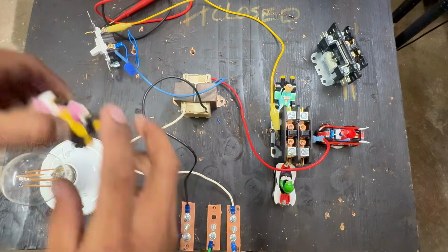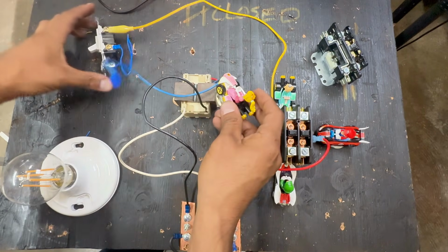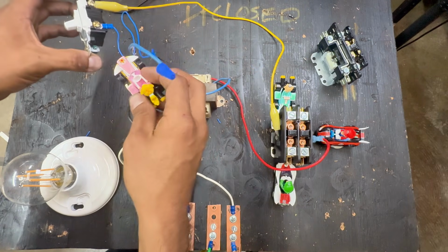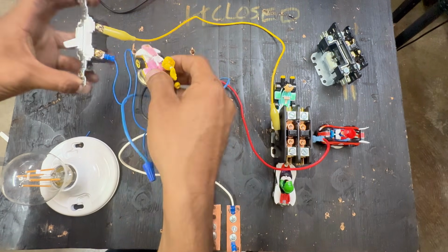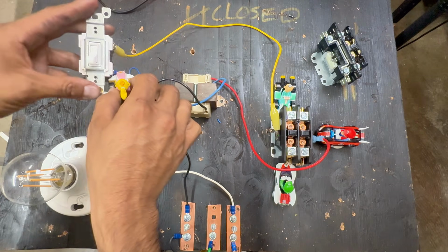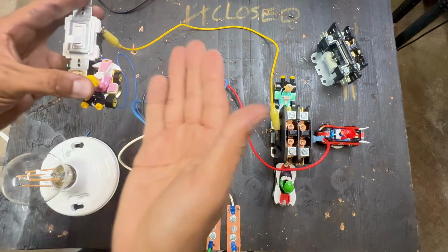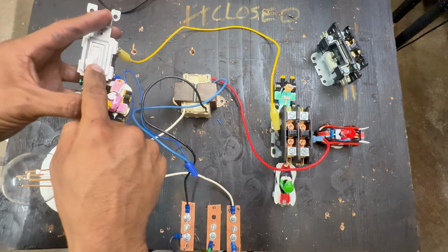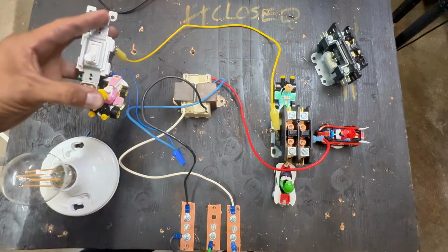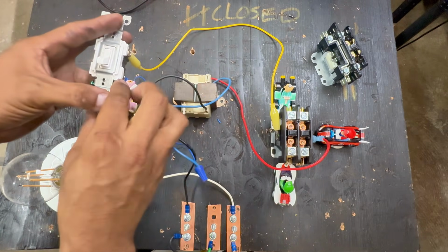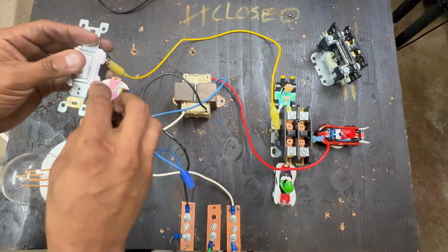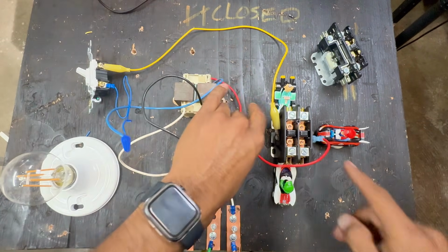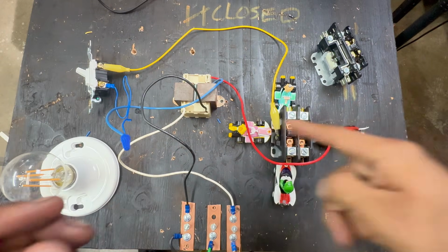So if we follow Peach, she's going to go through the wire here, right? You see the other wire? She's going through, she's going through, she's going through. Oh, she's stuck right here. And this is how the cooling works. When I have the thermostat and I have a call for cooling, remember, if it's a close on rise, temperature rises, it's too hot, the switch closes. And now I have power over here. Now I have 24 volts. Current's going back and forth, back and forth.